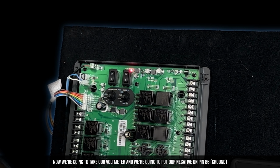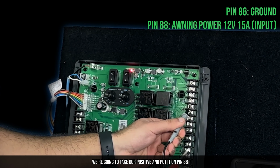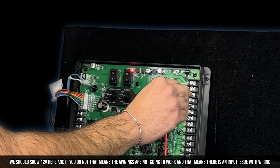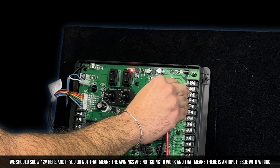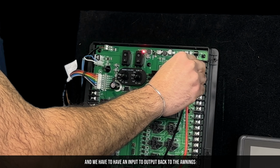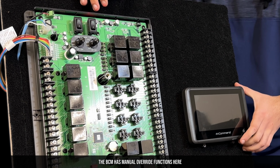But now we're gonna take our voltmeter and we're gonna put our negative on pin 86. We're gonna take our positive and put it on pin 88. We should show 12 volts here. And if you do not, that means the awnings are not going to work, and that would mean that there is an input issue with your wiring. And we'd have to have an input to output back to the awnings.